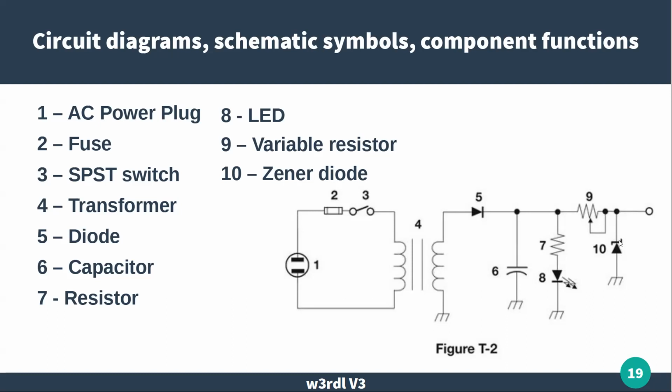So you can get one, let's say 5 volts, which means when you apply 5 volts in the reverse direction, it will conduct. And we use that as a form of voltage regulator with a resistor in series with it. It will maintain that 5 volts depending on the total amount of current flow or voltage drop across this.